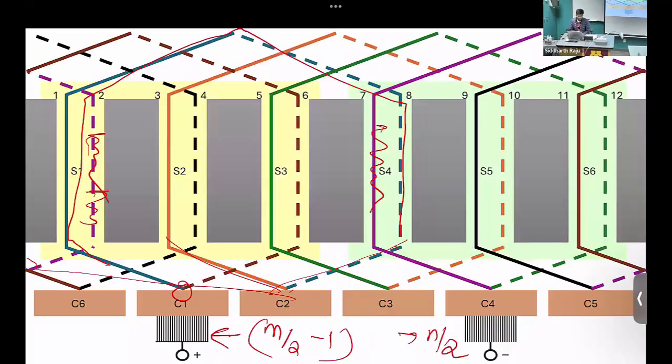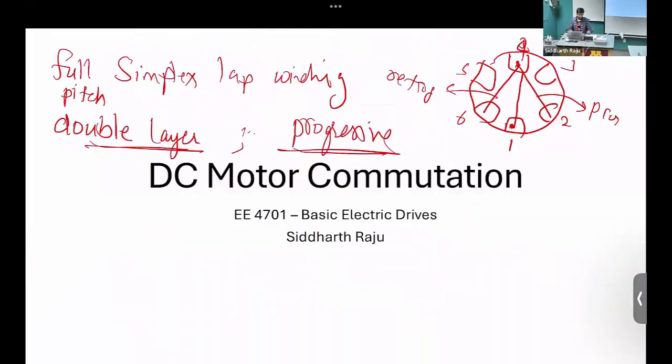Yeah. So if you were designing a motor, how would you choose which way you would prefer to do it? Random. Whatever you want. So between retrogressive and progressive, there is no advantage. It'll be whatever you want it to be. If you number the slots differently, you could have the same winding. Yeah, instead of going 1, 2, 3, 4, 5, I could have gone in the clockwise direction. That would have been the same effect. Yeah, that's a good analogy.